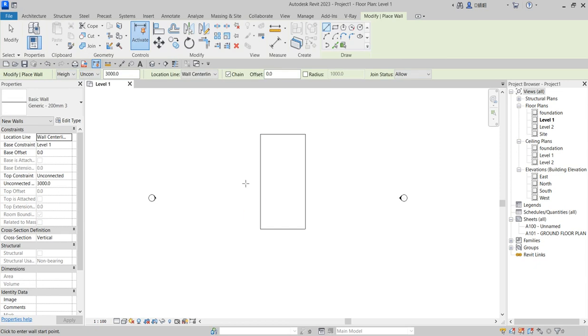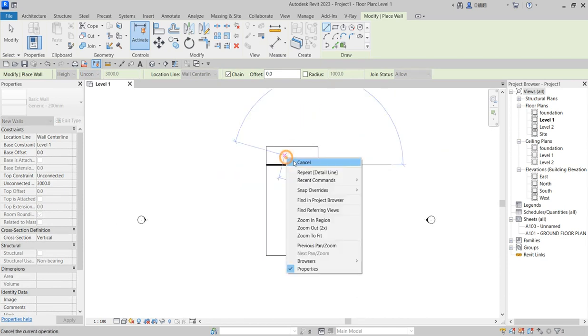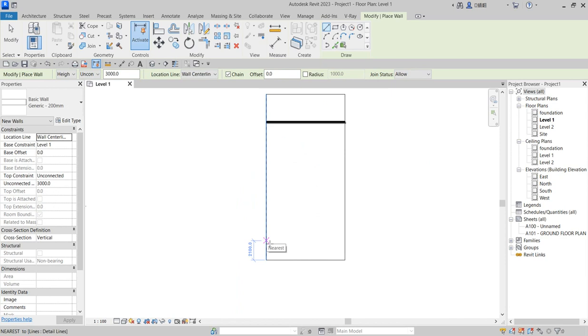Go to Wall. At the wall, choose the normal wall size that you know is functioning. So I'm choosing the normal wall size I know here. I'm starting here. The first thing I need to do is give a setback of, let's say, 3 meters because of parking space and the allowance and the setback at the front. So it's 3 meters. The developers in Lagos consider so many things before they decide. But one thing is that they look at their own money-making and convenience. So that is the point.